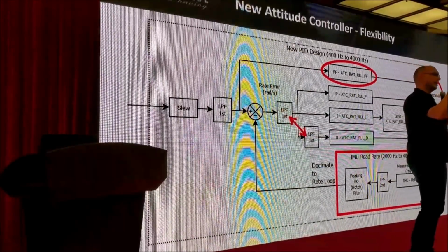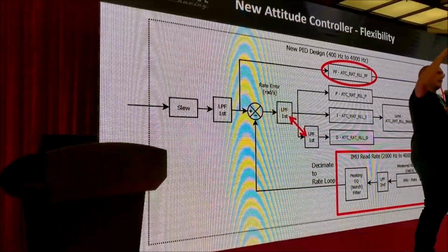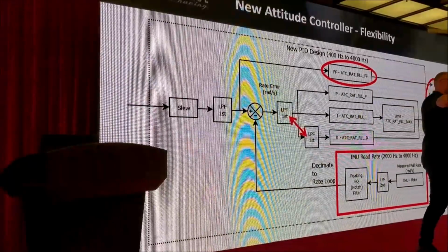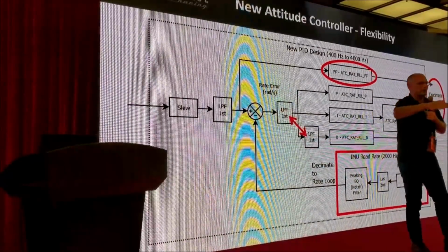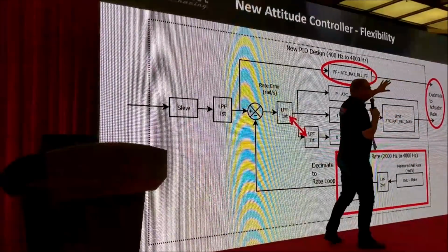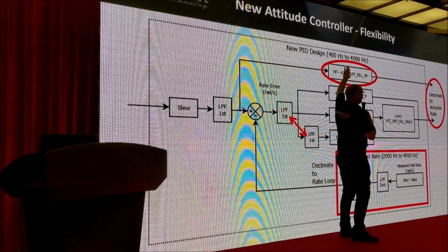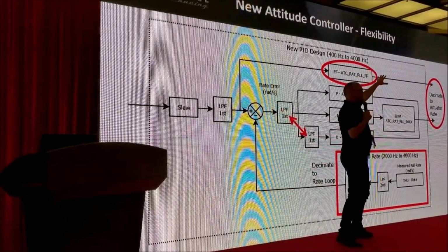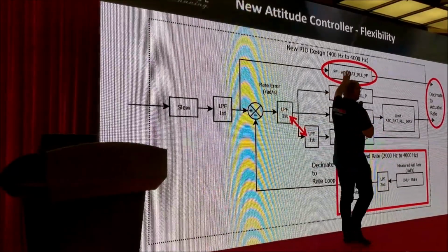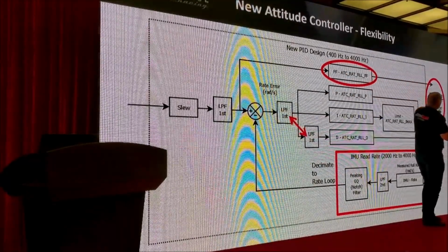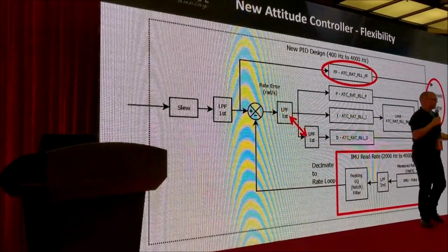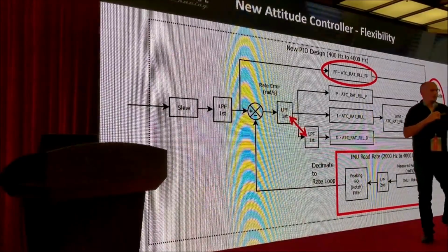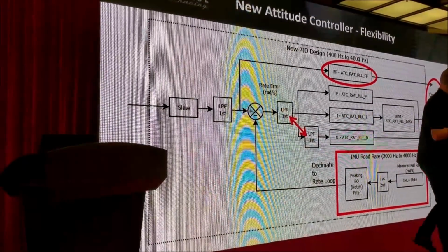So a tail sitter, a plane that wants to take off like this and then fly forwards. That aircraft uses moving actuators on the rear surface. In order to control those well, you need the feed forward, which is the part of the controller that does most of the work. And so by setting up our system to output that separately as opposed to together the way it is at the moment, we're able to accommodate the requirements of a wider range of aircraft and control types.